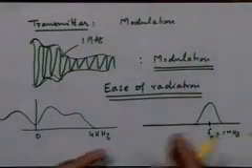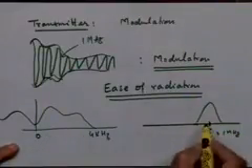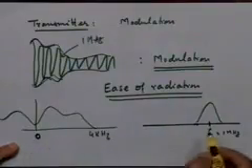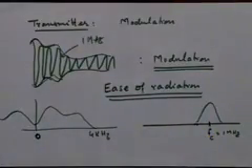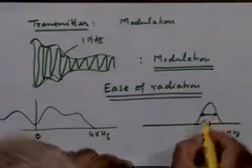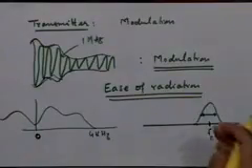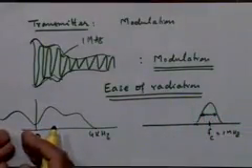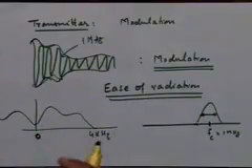So the important point is that the location of the spectrum is not around DC, not around zero frequency, but around some other carrier frequency, some other frequency FC. So we are not increasing the bandwidth. Bandwidth is the span of the spectrum, whether it lies in one frequency band or another. So you must understand the difference between the center frequency concept and the bandwidth concept.